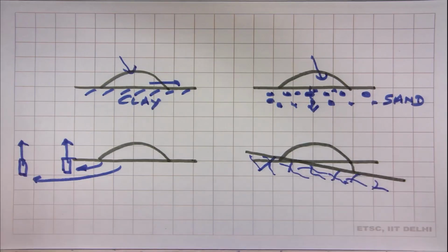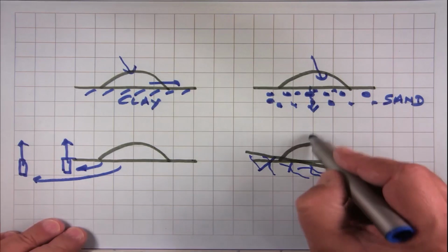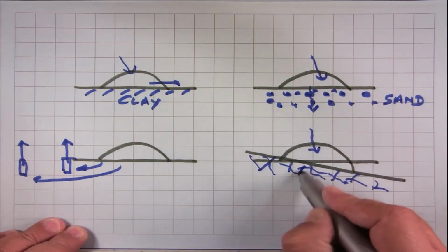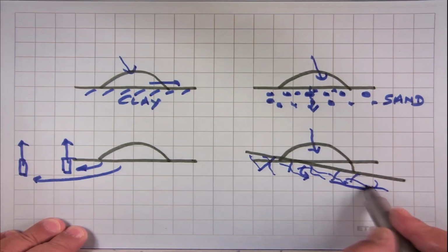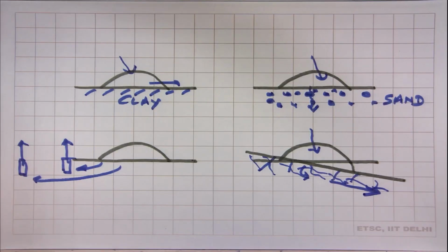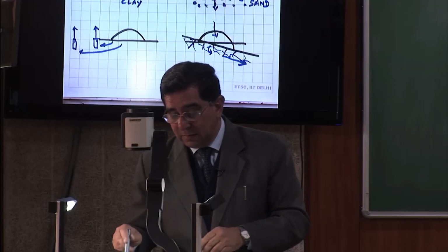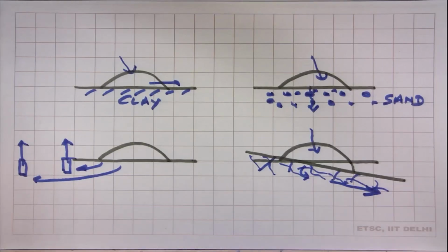And what happens? Rain falls, it gets into these cracks and then travels along these cracks. So competent rock is impervious, but we rarely have competent rock on the ground surface. We have fractured rock on the ground surface. So many a times you will find a shorter pathway, not because the distance is less, if the well, but because the permeability is higher.